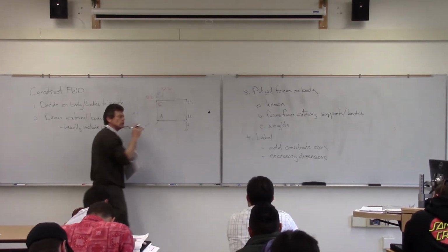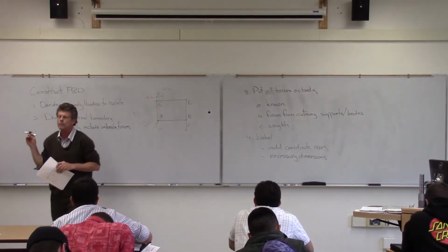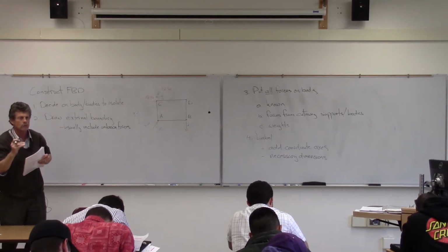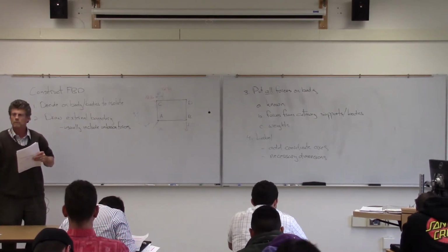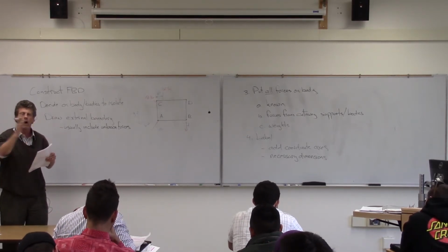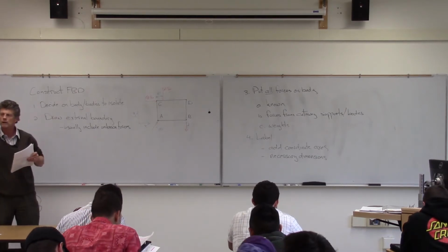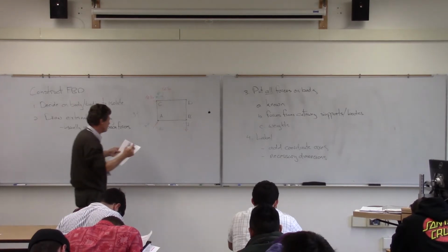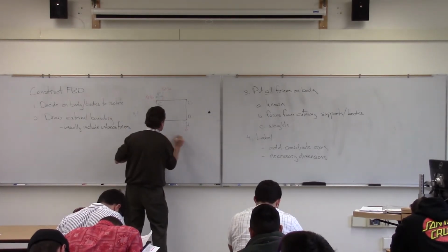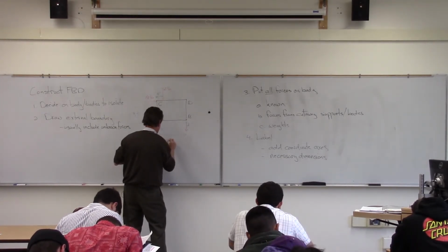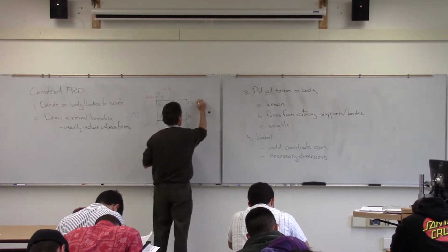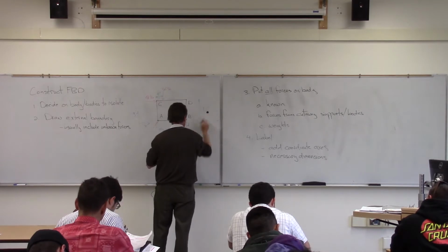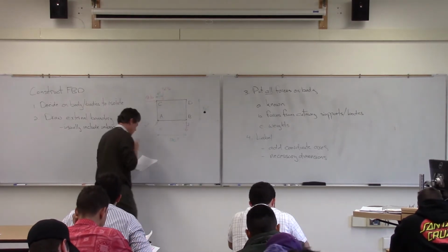But the reason why we do that is, again, remember, summing forces is just simply summing x components and y components. But summing moments, we've got moment arms. And we're going to need to know how far we're moving forces out of their lines of action to some point. So we're going to need those distances. So we've got the 4 inches there, 20 inches in the horizontal, and then 10 inches in that direction there.